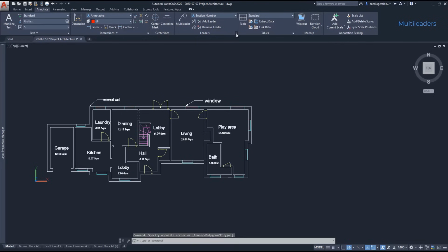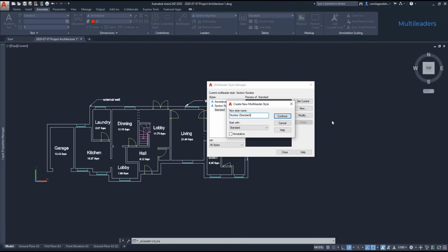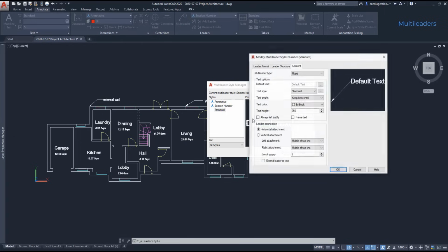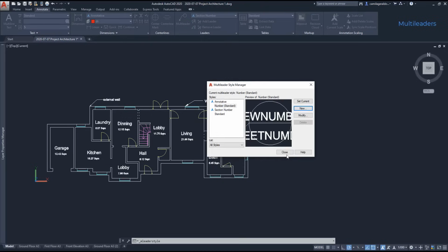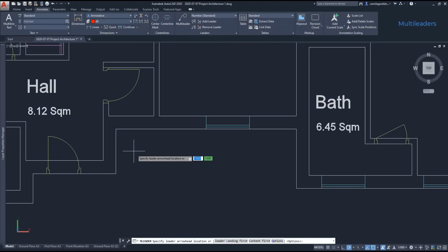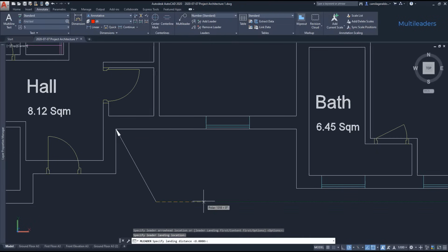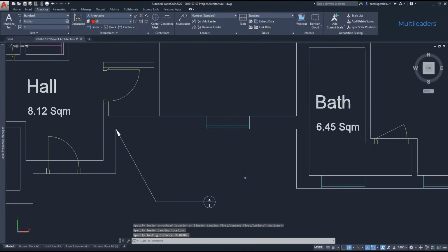In the next example, I'm going to add a multileader using a standard, non-annotative style. So, if I use the scale 1, it will be too small for the drawings that I have here. I need to increase it. Let's try with 20. Then I close this window. I'm going to draw the leader. And you can see that the block I have here is a bit different. This one has 2 attributes. I just put random values, and now the size fits quite well for this drawing.